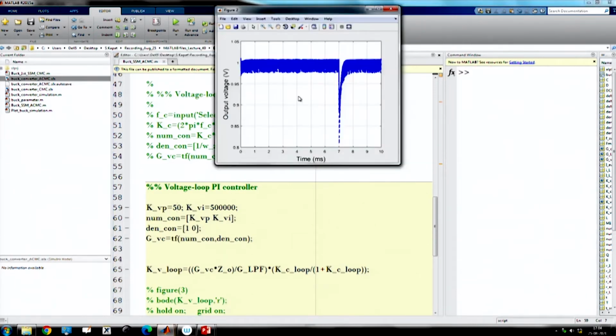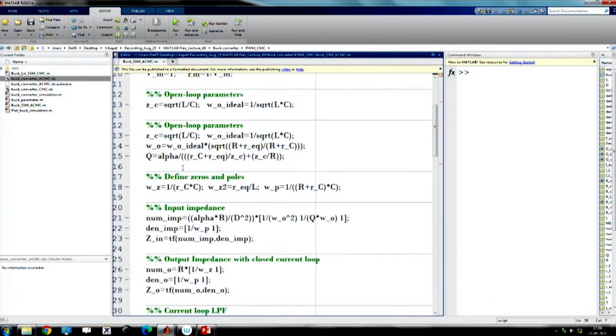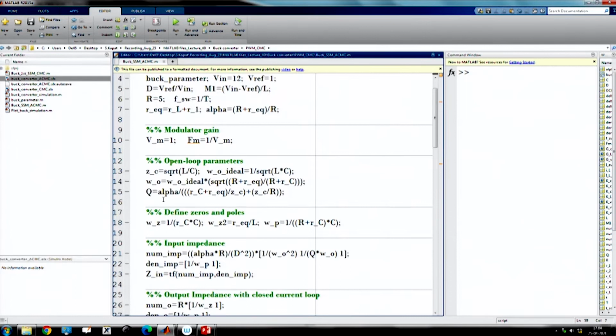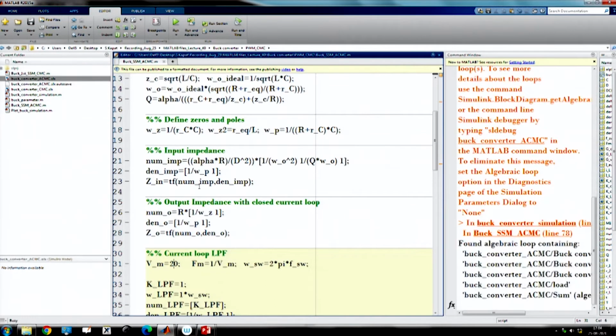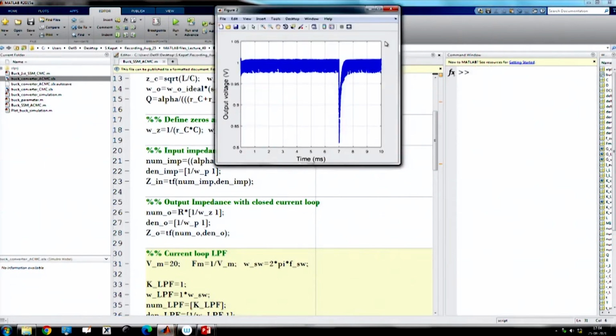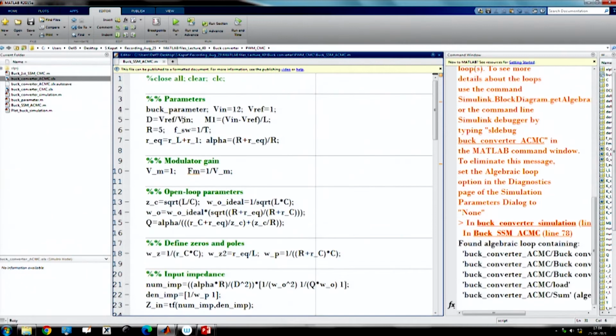So, we are slowing down, and by that way we are trying to stabilize, but at the same time we should also increase the compensating ramp effect, because the subharmonic is severe here. Okay, so we want to repeat it.